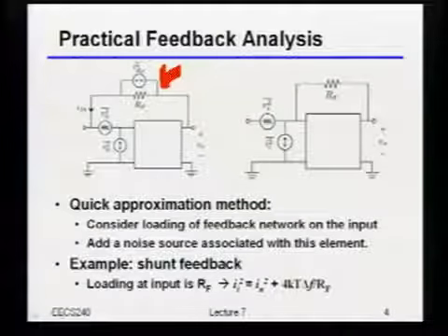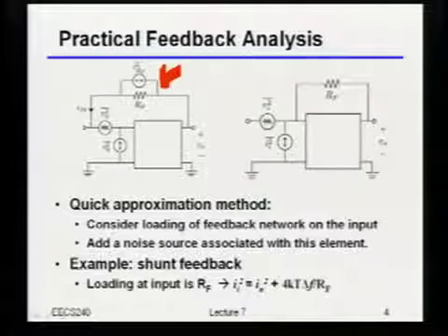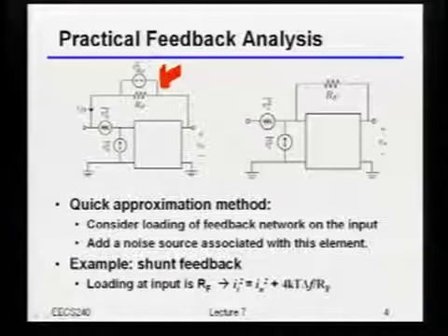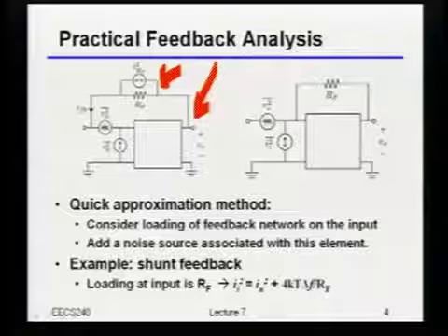Just as a reminder, if I have a shunt feedback circuit like this, what's the units of the input I should be using? In other words, what type of input should I be feeding it with? Voltage? For something like this, got it. Yeah, I want to feed it with current, right?